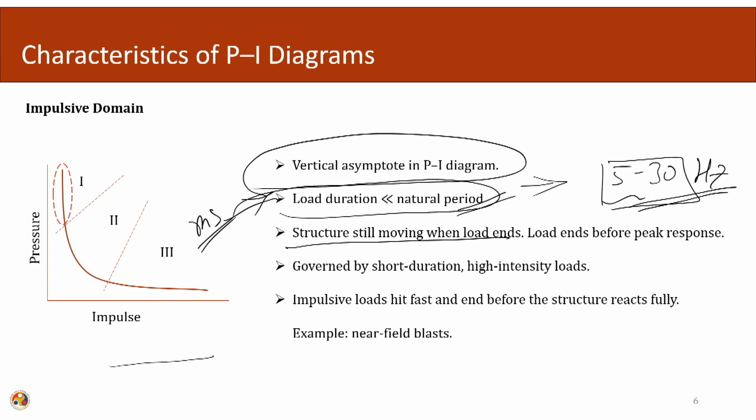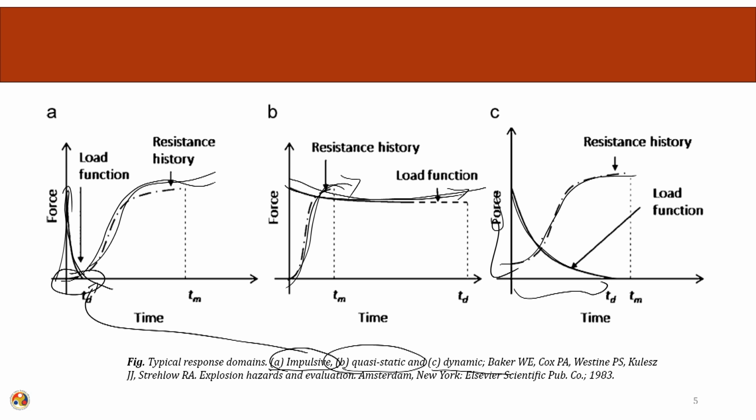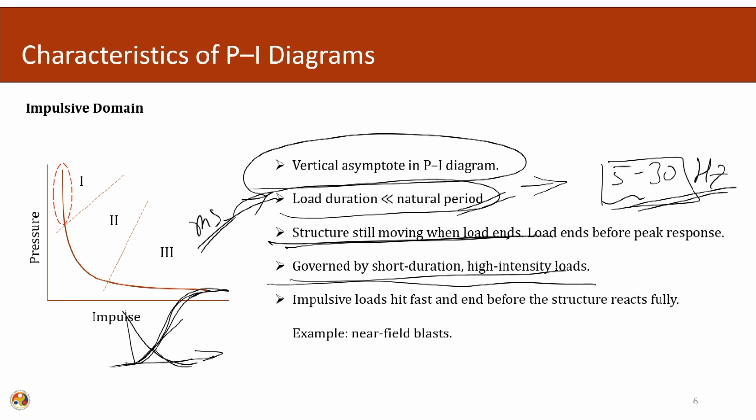So, the loading has ended, and the structural response has either just begun or it is continuing. This is governed by short duration, high intensity loads. The meaning of this, if you look at the previous graph, is that the loading has ended, but the structure has just started to move and is about to reach its maxima well after the loading has ended. In some cases of dynamic loading also, the loading has ended but the structural response is still undergoing. This is governed by a short duration, high intensity loading.